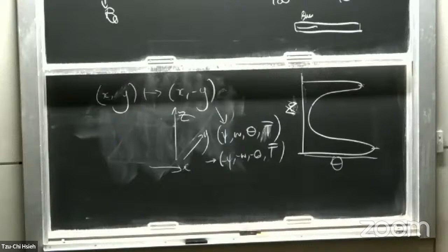Okay, so on this left-hand side, we're just seeing what this curve, the Nusselt number, is curving up now. So this Nusselt number is what you would get by solving the single mode solutions, Nusselt versus Rayleigh. But when we recast this problem, we can scale everything with regard to the Nusselt number, and we can get out the instability of the boundary layer at a critical Nusselt number where the boundary layer becomes unstable. Okay, so as you increase the temperature, there's a critical Rayleigh number where the boundary layer becomes unstable.